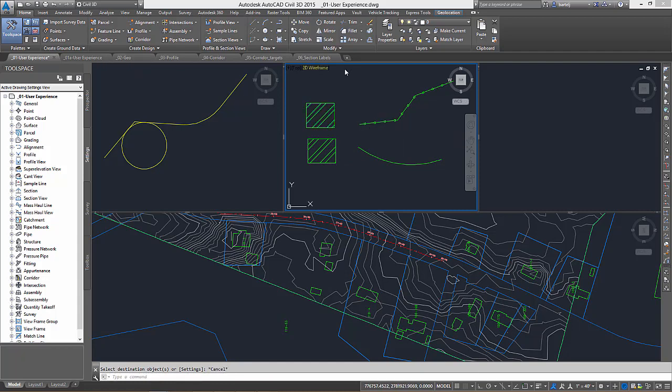I can also use match properties for some complex line types, which is kind of nice. When we hover over the top of it, we can see the effect of the line type before the command ever completes. And if we start to do things like grip edit the geometry, now we can see the effects of the complex line types before we ever end.